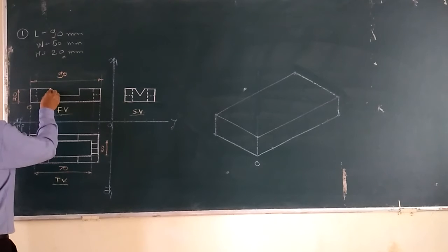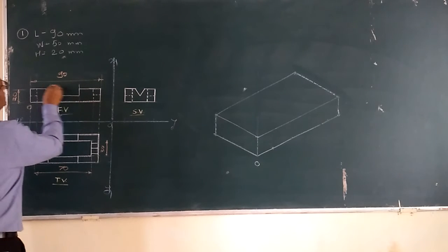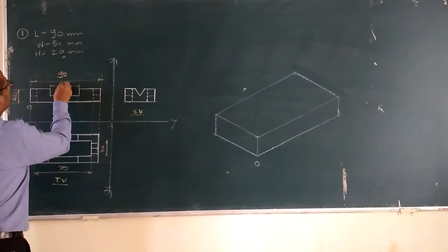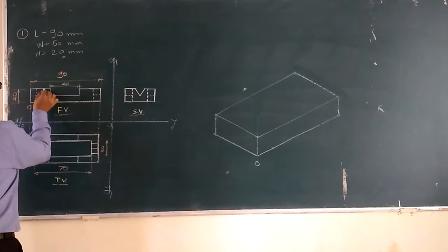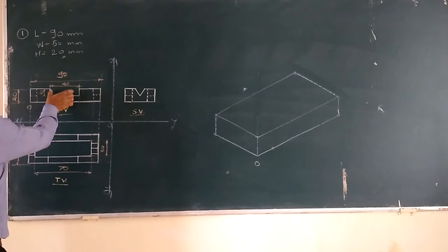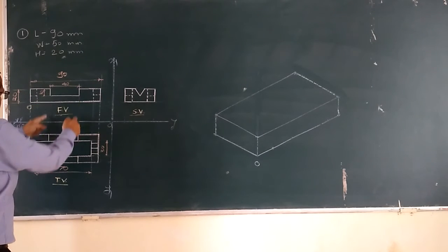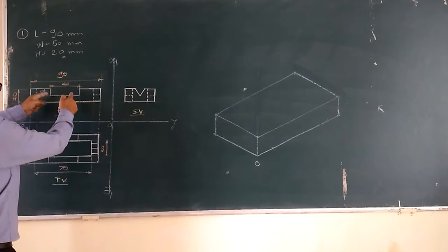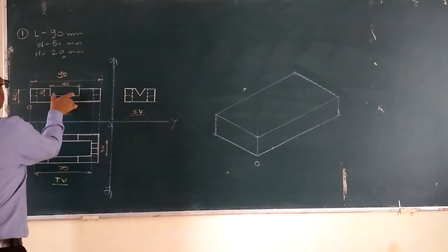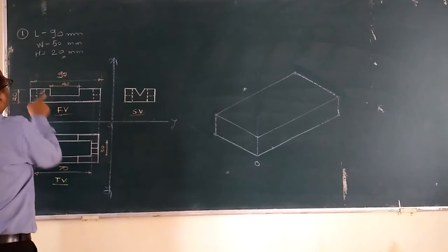This length of this slot is 40 mm, and it is carrying a depth of 10 mm. This part from both the walls, just observe, this slot gets projected in top here. See here, when you observe from top, after removing this cut, after removing this part, what will happen?